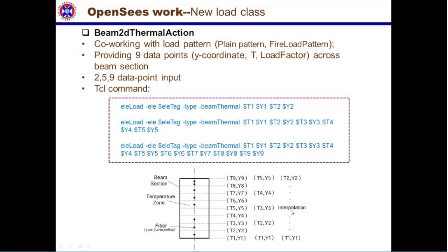If I can interject here, sorry, I had to run away to look at something else. This is one of the advantages of using OpenSees, because it allows us to define all these things ourselves. Like in Abaqus, we have problems defining the very steep thermal gradients which would normally exist in, say, concrete members, because it only allows 3 data points or 3 temperature points by default.